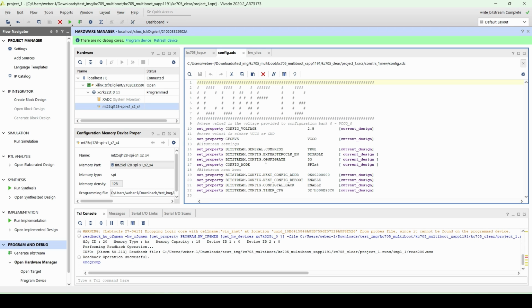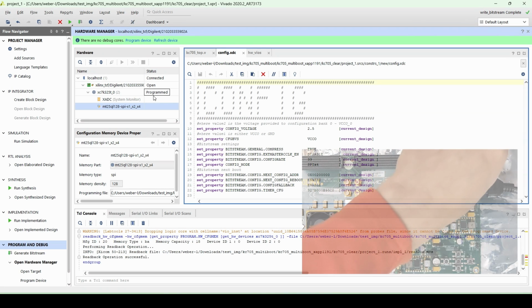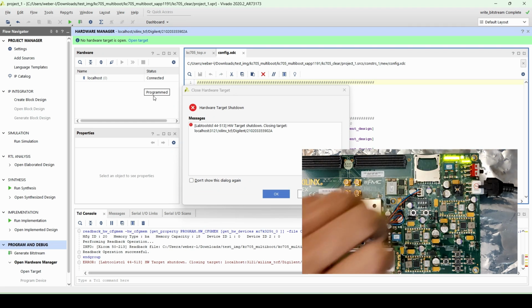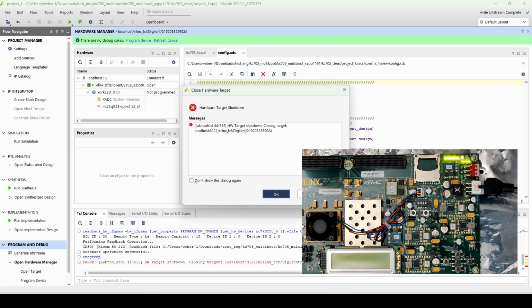Because in the Bitstream configuration here, we enable the Bitstream warm boot and jump to the SPI address 200K, and we don't have anything there at the moment, it's just like an upgrade process but failing with the upgrade SPI write. When the Golden image boots, it jumps to nothing, and because we have set a timeout, it will eventually go back to this base feature Bitstream and boot itself.